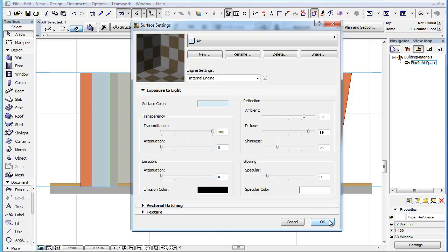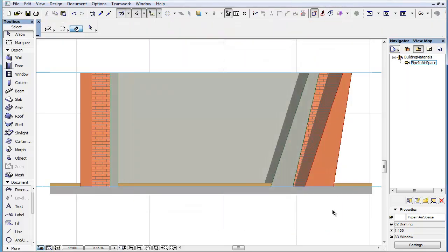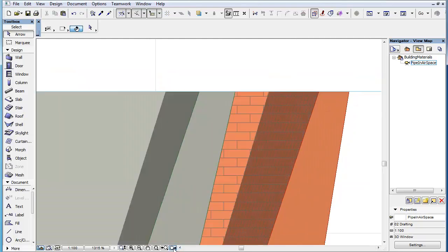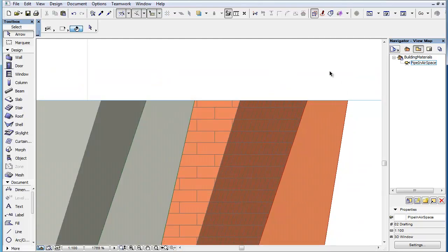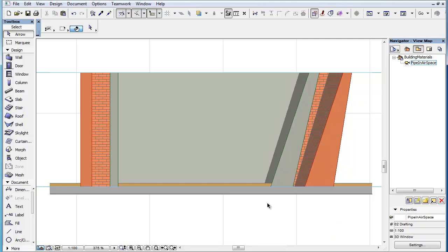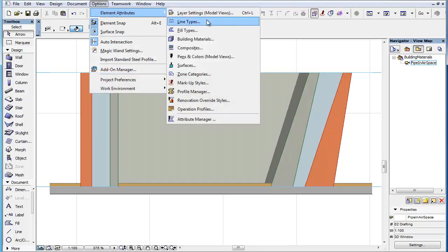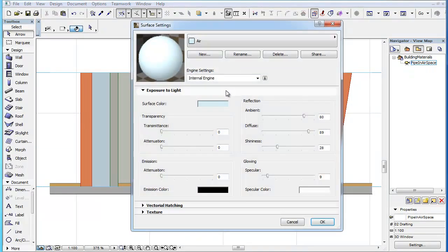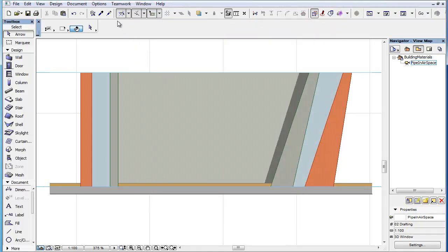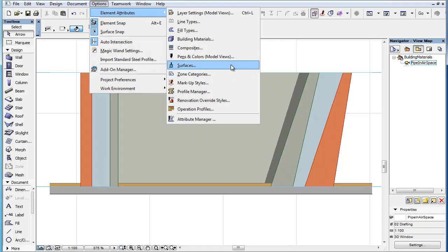Setting these 3 settings to the values mentioned gives us a fully transparent building material in section, elevation, and interior elevation viewpoints. It must be noted that the surface's transmittance settings have a more complex, more gradual effect in these viewpoints. If the transmittance slider is set to any value between 0 and 50, the building material will be opaque in the 3D document viewpoint.